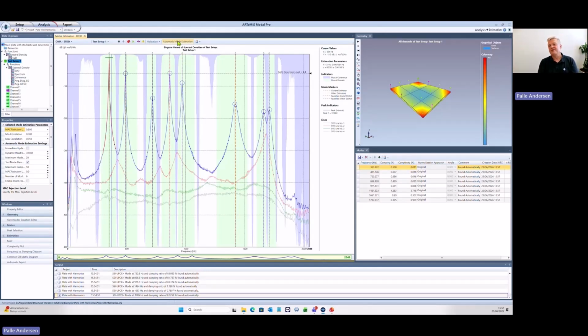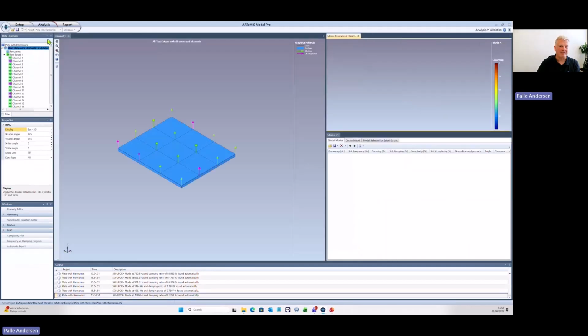So just remember that if you have difficulties with the spectra being flat or not so easy to see, switch to the SSI methods, because it's a kind of a black box. It can actually analyze the data, even though you cannot really see the peaks in a proper manner. So it's nice to have different tools in the toolbox, and that's why we favor our pro version of the software that has up to 8 different tools in parallel.